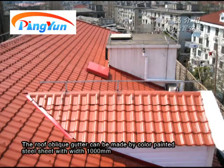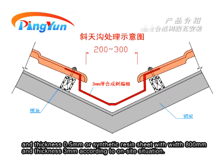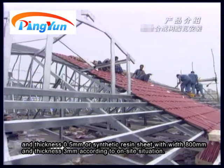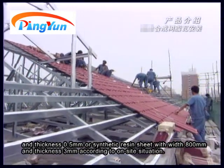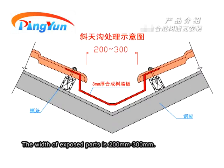Installation of oblique gutter. The roof oblique gutter can be made by color painted steel sheet with width 1000 mm and thickness 0.5 mm, or synthetic resin sheet with width 800 mm and thickness 3 mm, according to on-site situation. Before main tile installation, the oblique gutter should be installed on purlins. The width of exposed parts is 200 mm to 300 mm.